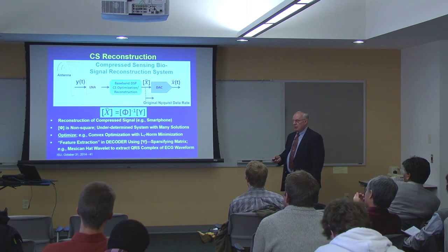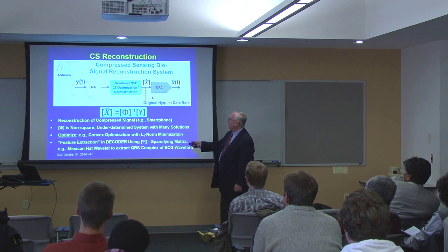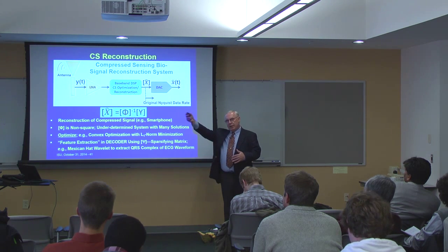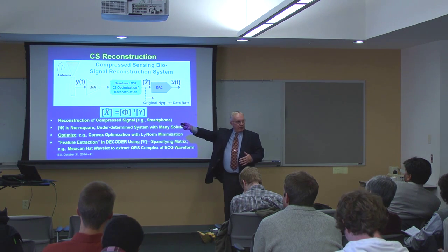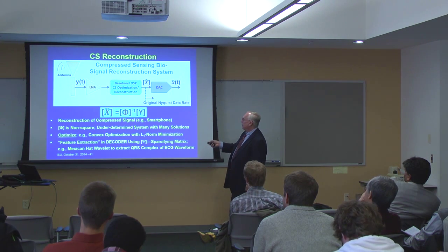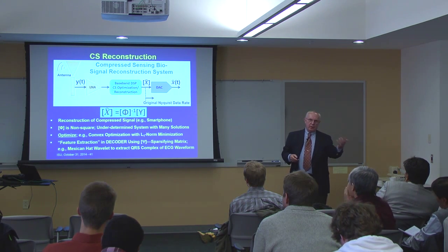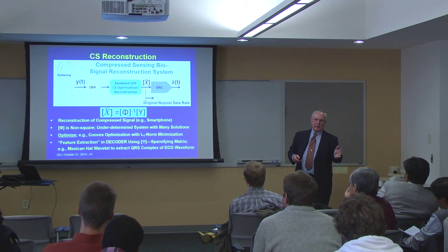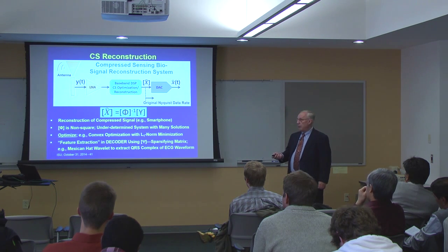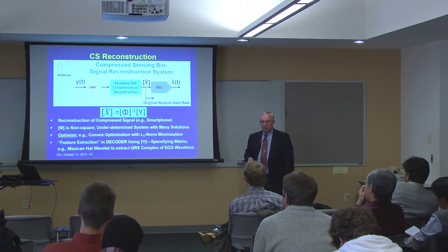So a little bit about how the system works here. We know now how to take our signal, bring it in, and compress it. So once you compress it, you transmit the digital information back to the hospital, to the doctor. There's an antenna, picks it up, and reconverts it back to digital. Now, this is a very asymmetric process. The part of gaining the data and compressing the data is very efficient, very easy. The reconstruction process can be very complicated because you can put this so-called baseband DSP there.